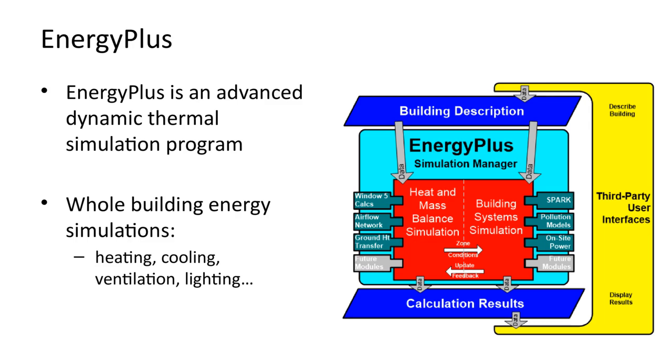In this case, the spatial model needs to be converted to the EnergyPlus representation. The representation focuses on the requirements of thermal simulation. It is a text-based file called an IDF file. Along with the spatial model, many other settings need to be specified to describe the building materials and systems.